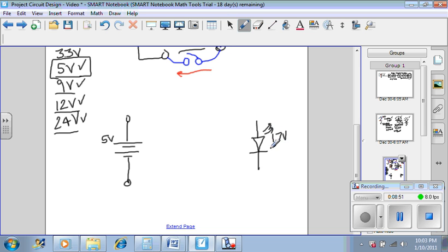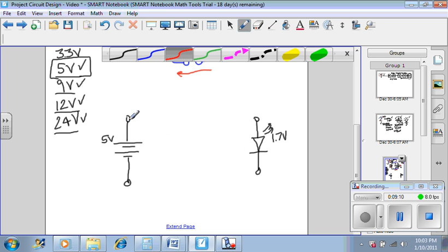It can probably operate at more or maybe less than 1.7, but ideally we want to be as close to 1.7 volts as possible because this LED is very sensitive. Well, most electronic engineers know that if you join 5 volts across a component that only operates at 1.7 volts, then you're going to get a damaged component. So that's not the right thing to do.